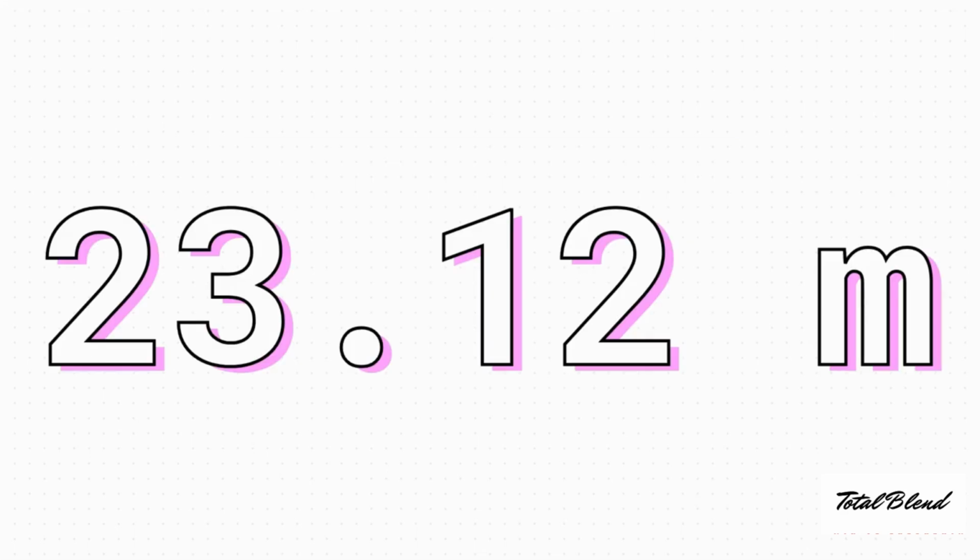First, let's use the quick and easy method. We take our numbers, we grab a C value of 140 for copper, and we plug it all into the Hazen-Williams equation. And boom, we get an answer. A head loss of 23.12 meters. It's simple, it's fast, we're done.